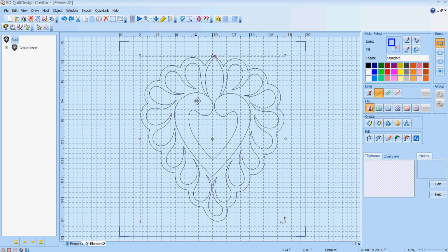Okay. In 4D, in order to have this as a standalone design without any fill inside of it at all, what you have to do is create a shape around it. And so in order to do that, you have to draw some lines. I like to use the polygon one because all I have to do is click some points, and with the other one it draws the line, and it's kind of a little bit more difficult to keep some kind of accuracy with that.